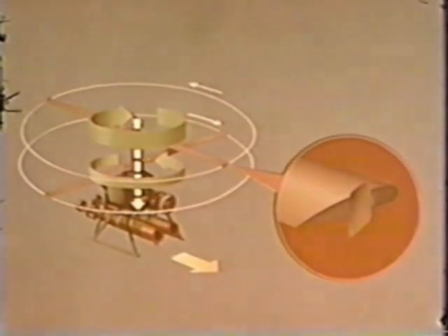They are small vanes at the tips of the blades. When they are extended on one rotor assembly, they produce aerodynamic drag. Thus, the drags of the 2 rotor assemblies are not equal. The reactive force feeds back through the transmission gears and turns the fuselage. The brakes on the upper rotor provide clockwise changes in heading. Those on the lower rotor produce counterclockwise changes of heading. When the tip brakes are returned to neutral, rotor drag is equalized and the fuselage stops turning.